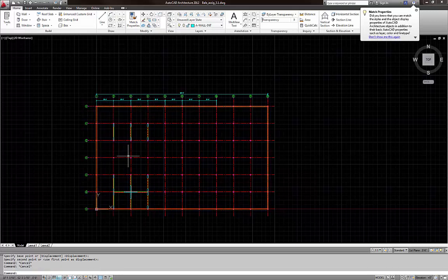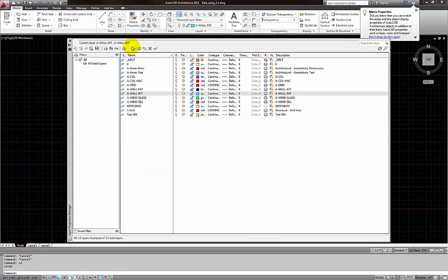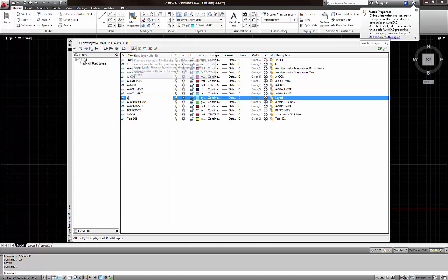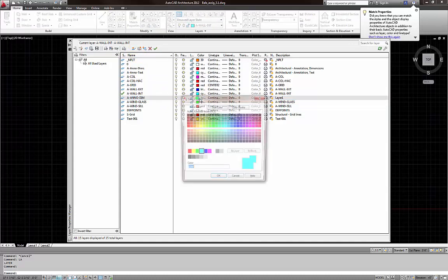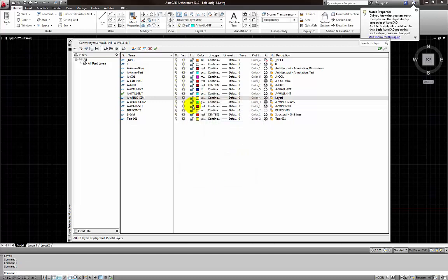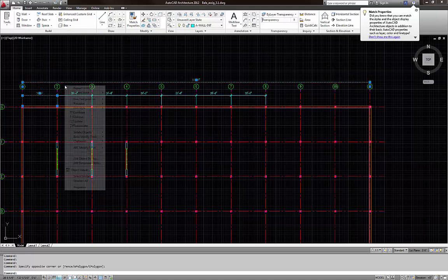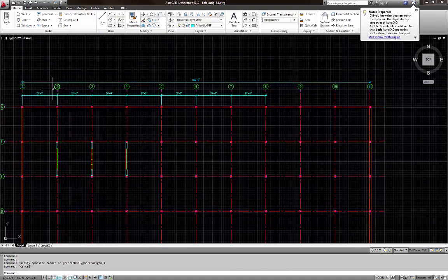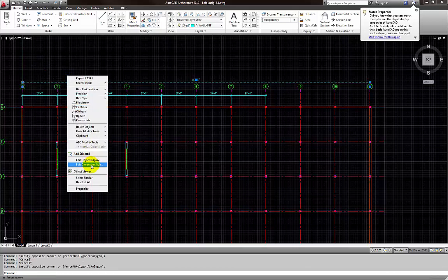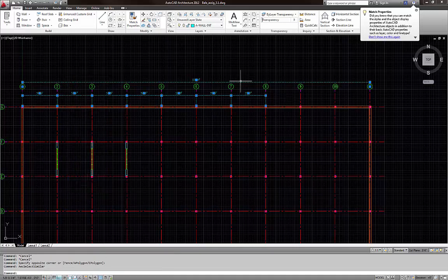And also please again create a dimension layer. Please go look at the Excel file and create a new layer, this time NODIM, and it should be yellow or green or red, and close it. I'm going to take this dimension line. See, when you click on one dimension, right click, select similar. See that you select all of this. It's a shortcut.